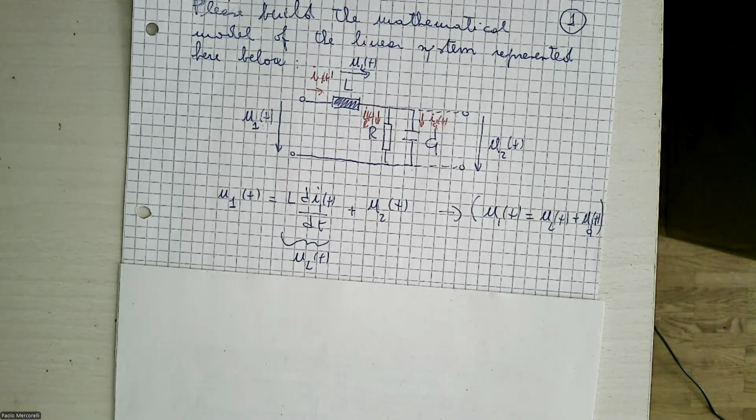Do you remember last time I told you that if I introduce the Coulomb friction, we have a model which is nonlinear. This means sometimes nonlinear is not so easy to control. Nevertheless, this system can be controlled, because we have a relatively direct relation between the voltage on the capacitor, this is U2, and the temperature which will be established inside.